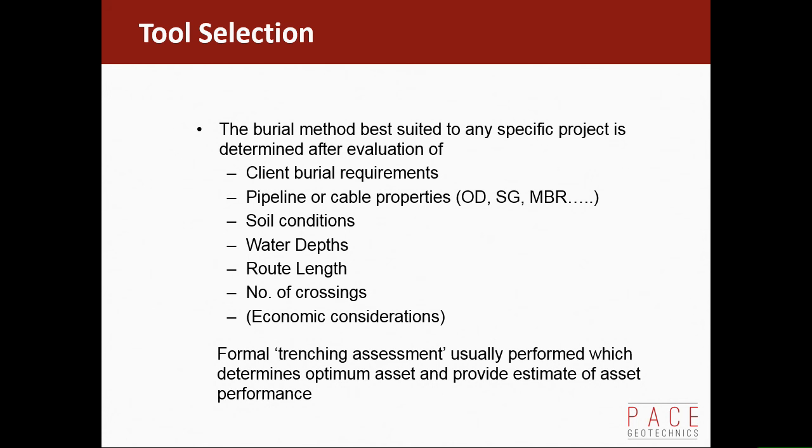So it's important that you understand the burial requirements, the seabed conditions, water depths, because some trenchers are very difficult to use in some particular water depths. Clay ploughs are very difficult to use in deep water and very shallow water as well. Things like route length.